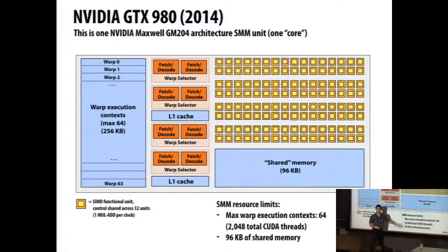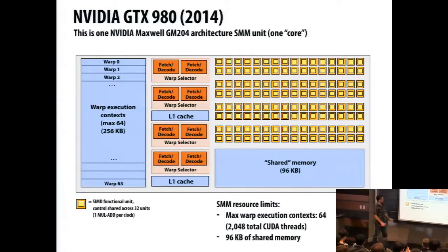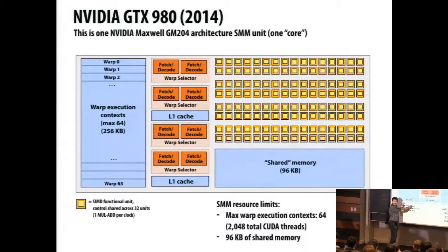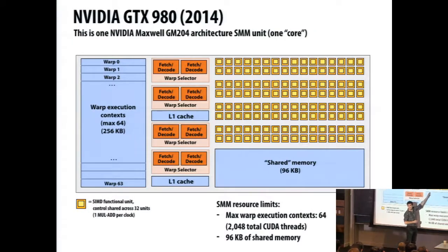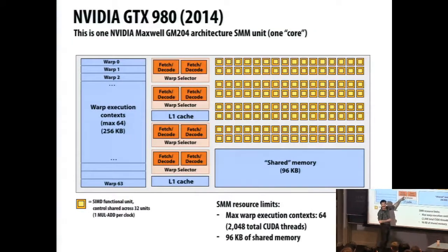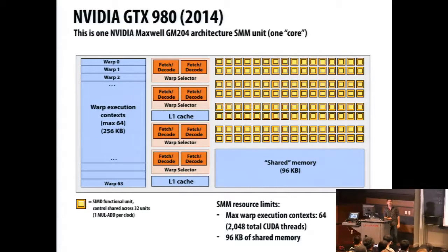So there are some other execution units that can do some other stuff as well. In terms of lecture 2, what is this? This is a core: 64-way multi-threading, 32-wide SIMD, 2-wide ILP within a thread, and actually simultaneous multi-threading, in which we can run up to 4 warps at the same time. Nothing new here, just being pushed to a much larger degree than what you see on an Intel processor.